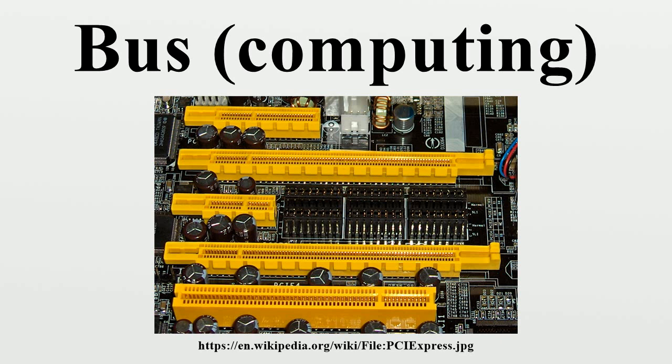They typically separated the computer into two worlds, the CPU and memory on one side, and the various devices on the other. A bus controller accepted data from the CPU side to be moved to the peripheral side, thus shifting the communications protocol burden from the CPU itself.